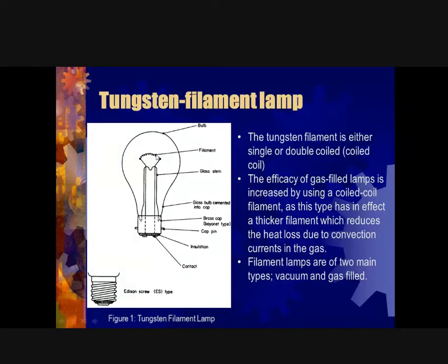That tells you that the lamp is blown. Now there are two types of filament lamps in terms of the base or the connection. You have the Edison screw type, which was developed by Edison, and you have the bayonet, or push in and twist type, which is shown here in the diagram. And on the left of the picture, this is the Edison screw type.